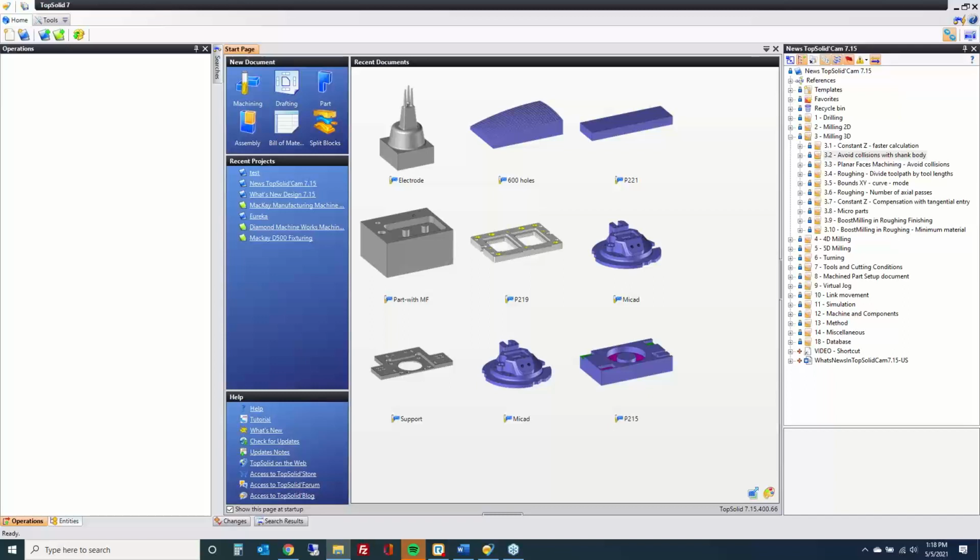I see a question there. How well is stock management update working with 3D Toolpath? If you're doing stock update for 3D Toolpath, use faceted stock. Using true solid stock update, you can try, but as we're doing real-time Boolean operations, if you have any type of tool with a radius on it, you might get errors in the stock update. If you use the faceted mode, it's relatively fast. It's like verify, in fact, and it works fine.